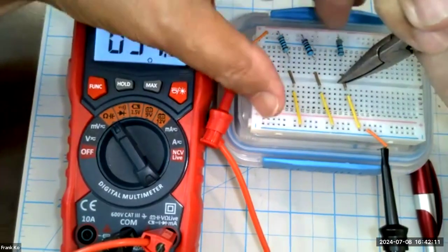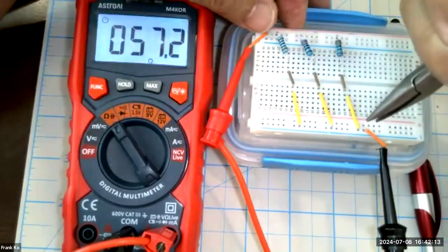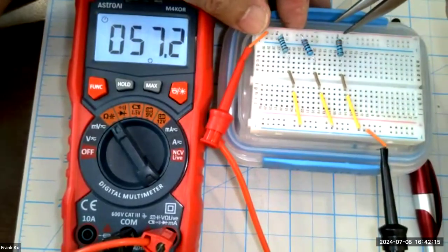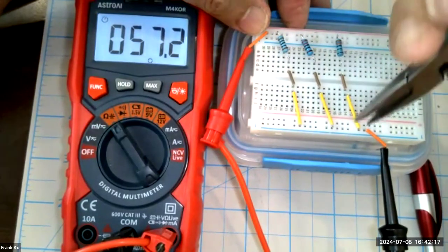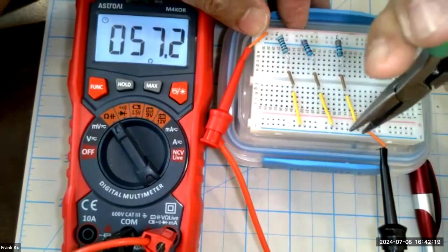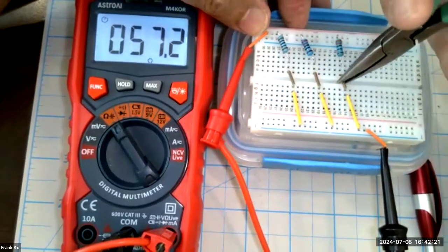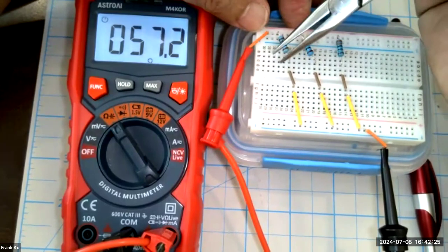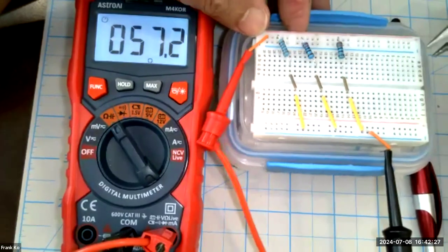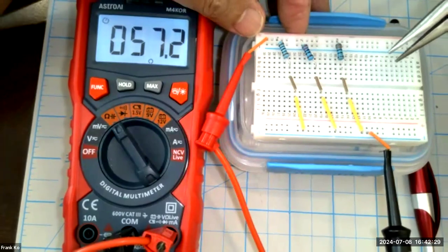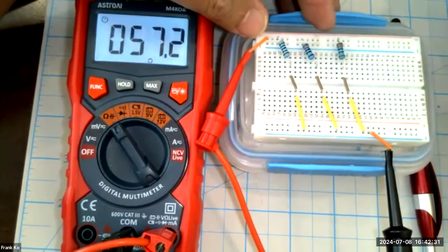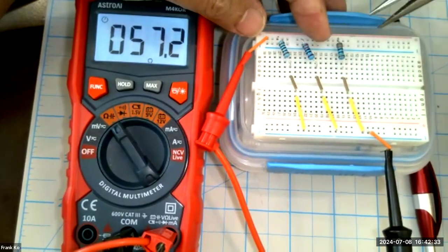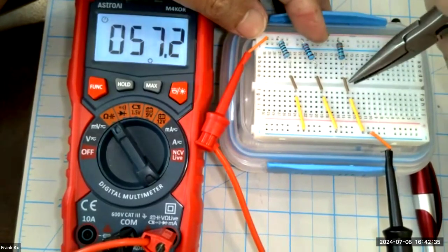I'm just going to conveniently yank it up for a moment. If I yank it up, won't it pull R3 out of the circuit? There will be no continuity between R3 to the red rail and R3 to the blue rail if I yank this jumper. And once I yank this jumper, all I have in parallel are these two resistors. And that's why the first calculation was R1 parallel with R2. You calculated 68.75. I calculated 68.75.